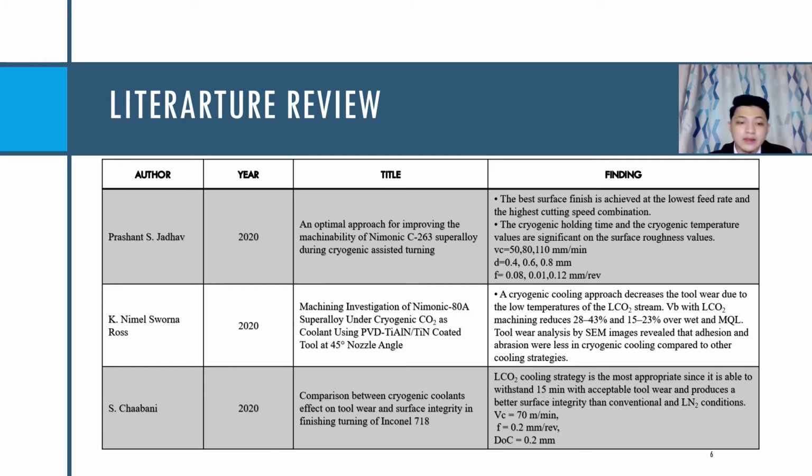Other than that, S. Jebaraj also wrote in an article with the title Comparison between cryogenic coolant effect on tool wear and surface integrity in finish turning of Inconel 718. He found out that the liquid carbon dioxide cooling strategy is the most appropriate since it is able to withstand 15 minutes with acceptable tool wear and produce a better surface integrity than conventional and liquid nitrogen conditions.